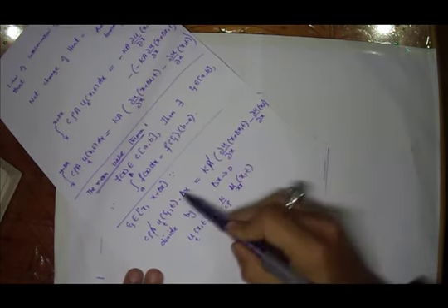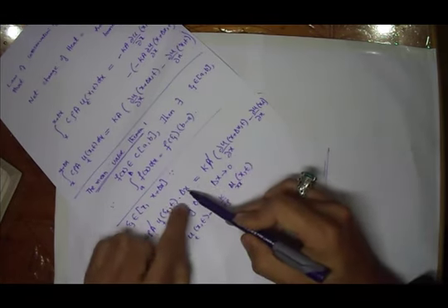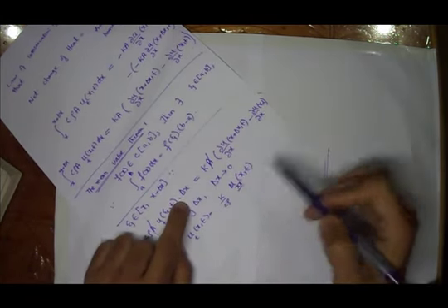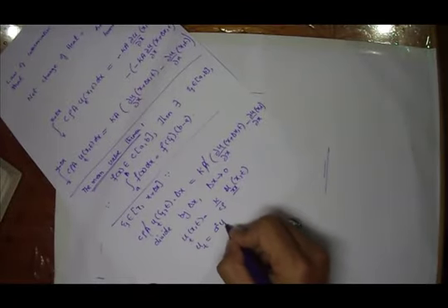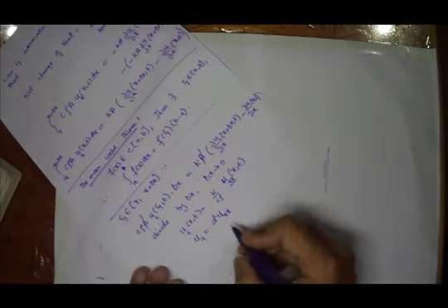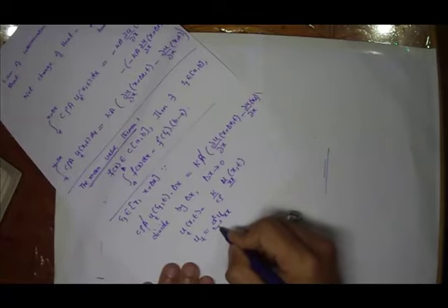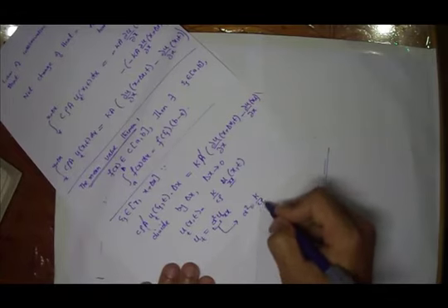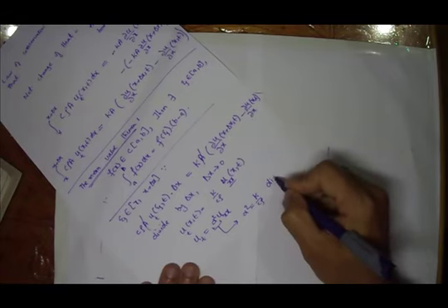Now if this quantity is divided by delta x and we let delta x approach 0, this is basically the definition of the second derivative. Let's use another notation. u_t is equal to alpha square u_xx. Alpha square is basically equivalent to k over c rho, and this is called the diffusivity constant.